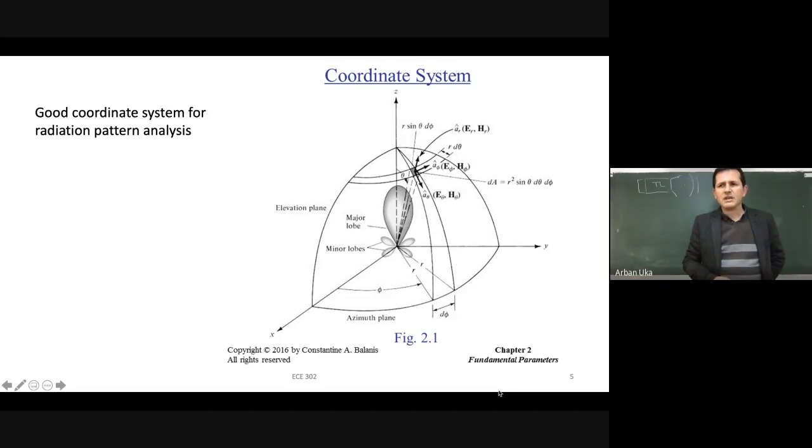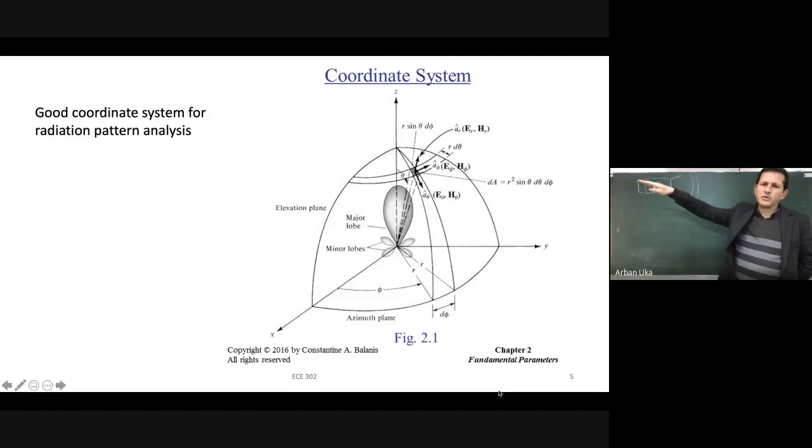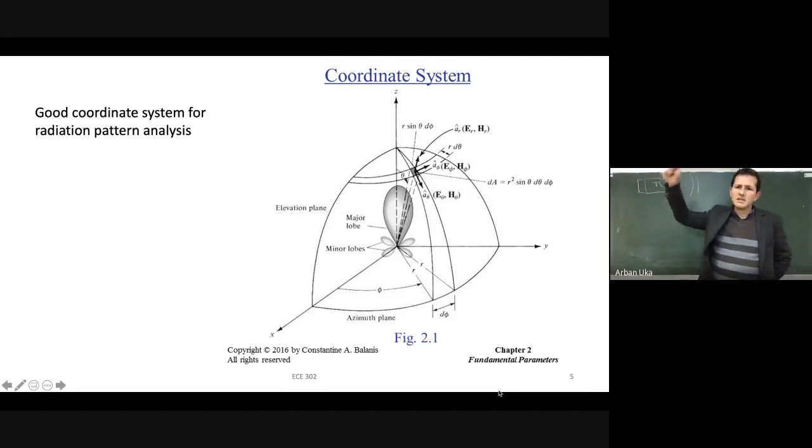Because the intensity of the antenna, or the power that we can measure at any point, is independent of the angle, which means that if we are at some respective point, we are so far from the source that the intensity will depend mainly on the radius. That is why the spherical coordinate system is the most appropriate. In the most general sense, we always make approximations, because if we do an expansion of the power of the antenna, most probably we have some nonlinear terms which make the numbers that we measure approximate and not exact or precise values.